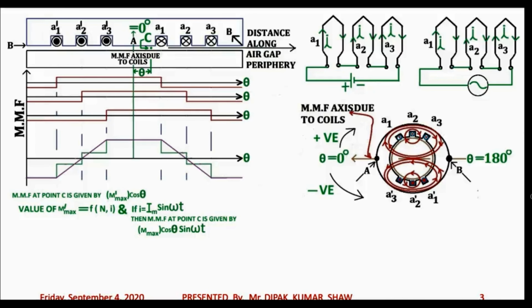So this cross sectional view is indicating that the magnetic lines of flux which are plotted are going to result into how many poles? They are going to result into two poles, because you see at the stator core, where the point B is there, you may follow the mouse pointer, please, the magnetic lines of flux are leaving the stator core.